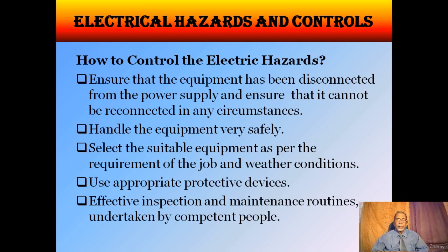You should select suitable equipment as per the requirement of the job and weather conditions. You will have to see two things. One is what type of job you are doing, and for that, what type of equipment you need. And another thing is, because it's electricity, you should consider the weather conditions, whether it is wet weather or hot weather or it's raining. You will have to consider all these things.